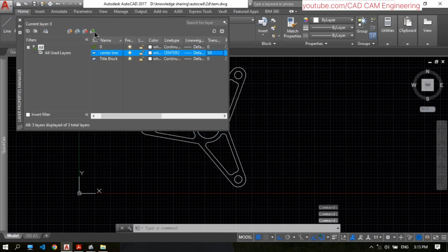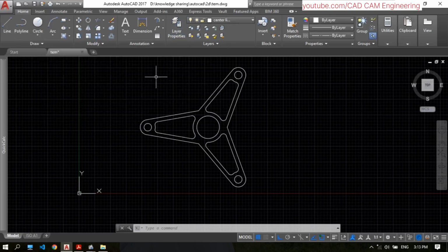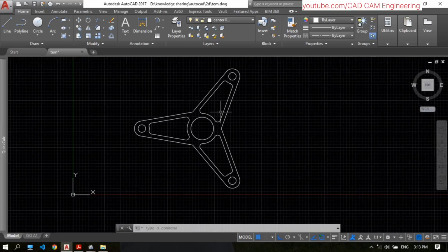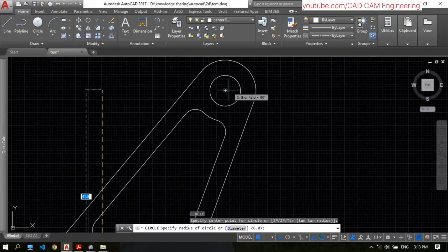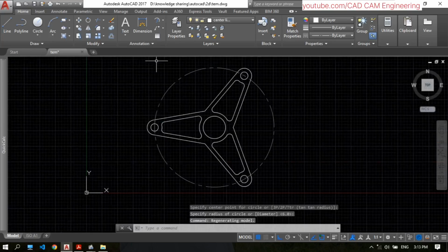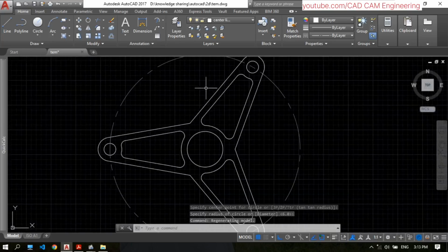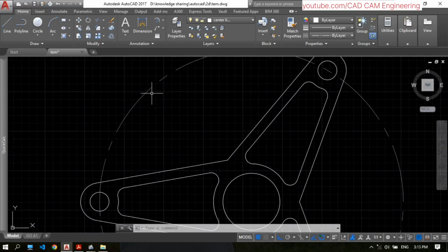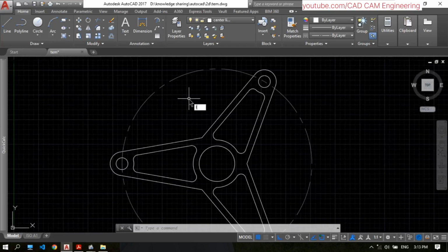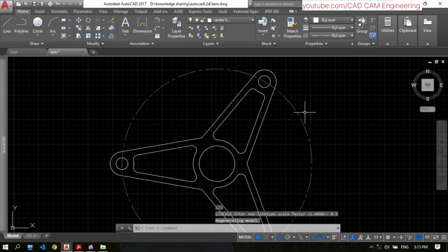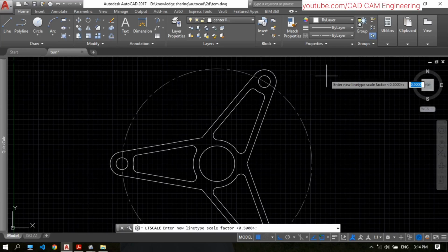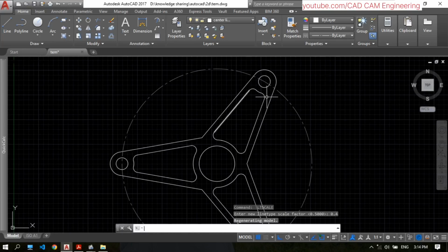and then center line, edit the center line, so you can mix the green edits. Okay, so C for the circle here splits the center line, so you may make it the center dim line. Okay, you can adjust the amount of line, the LTS line dash scale, that should be 1. You can adjust the line as you want. This is 0.5 and then 0.4 and then 0.3. 0.3 is okay for me.